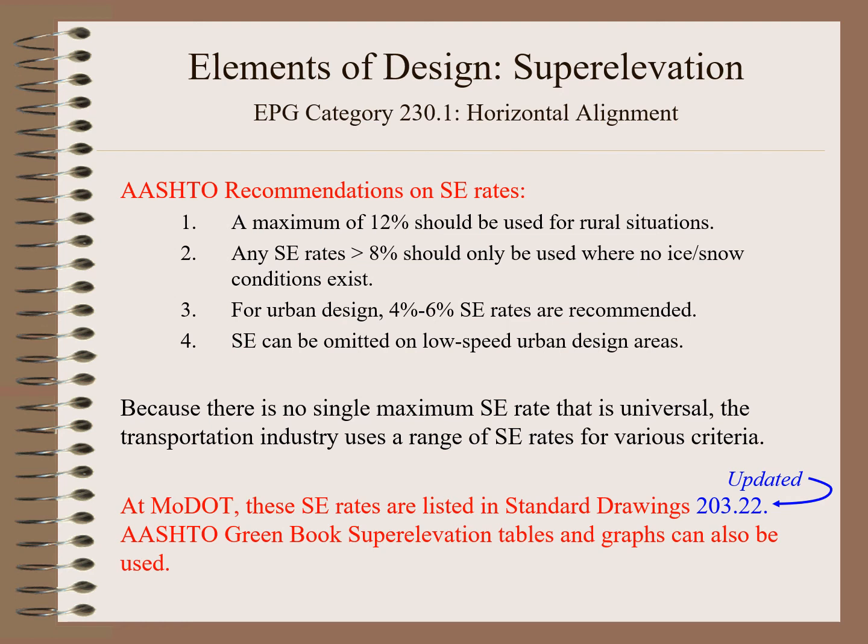Because there is no single maximum superelevation rate that is universal, the transportation industry uses a range of superelevation rates for various criteria. At MoDOT, these superelevation rates are listed in the standard drawings 203.20 and 203.21. AASHTO Green Book superelevation tables and graphs can also be used.